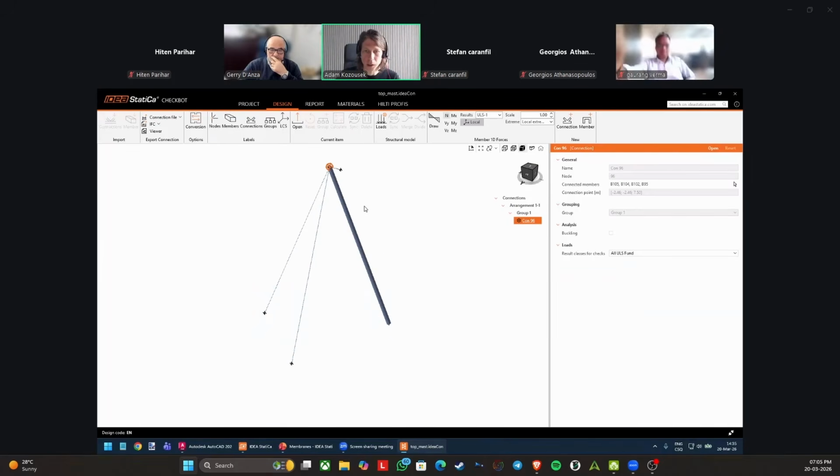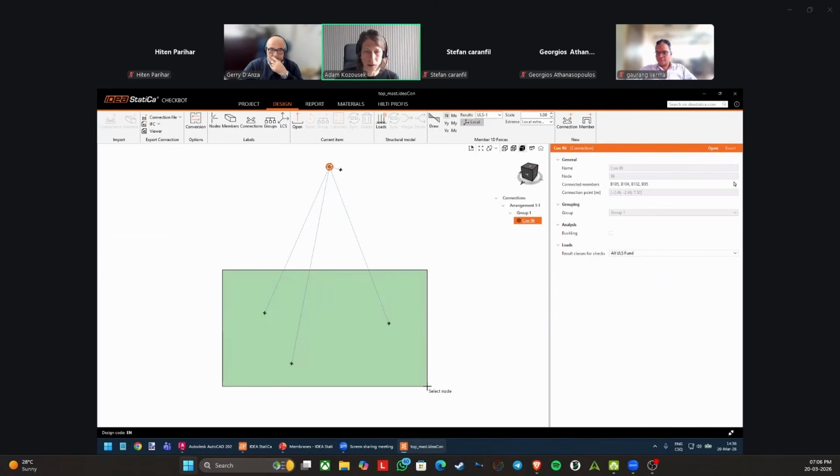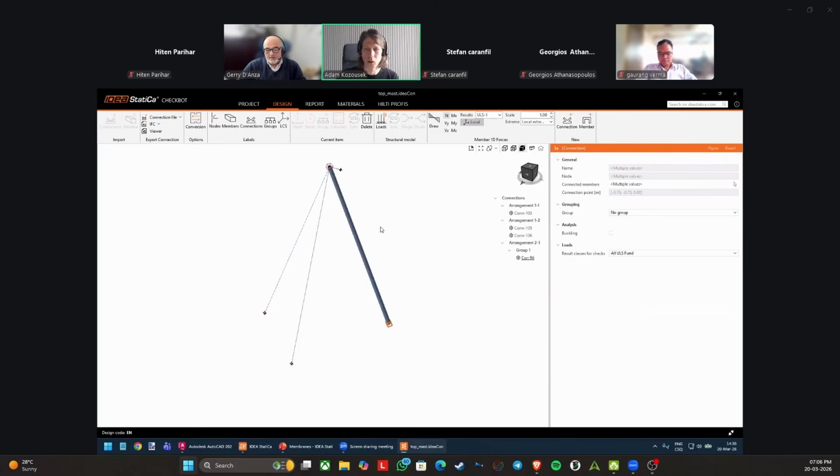But once you export one node from any FEA software, you export the surrounding structure as well, and the end nodes of the surrounding members. So the data that you need for these connections, for these nodes, are included as well. And there is a simple trick how to add these connections to my list of design items: I use this add connection. I select these nodes that are empty now. I will press spacebar or right click or enter. And now these nodes are populated with connections.